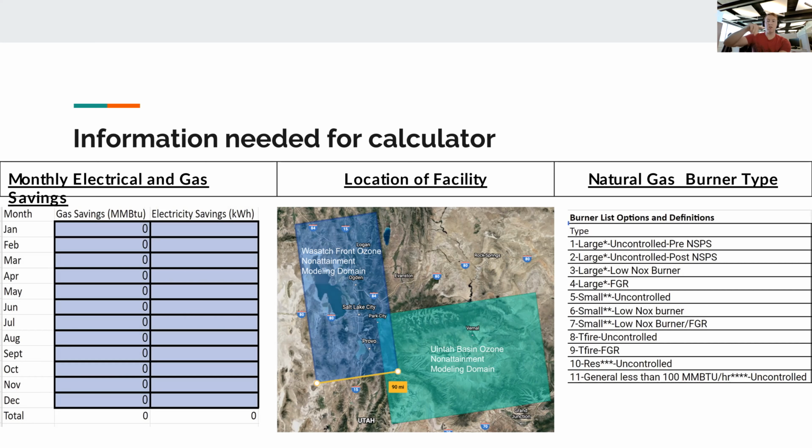That should give you a spike that you would expect during the hottest months. You would expect to be saving more electricity during hot months. And conversely, for natural gas, you should expect to save the majority of heating gas during the coldest months. I would use outdoor air temperatures if you have no other better way to estimate the monthly variation.